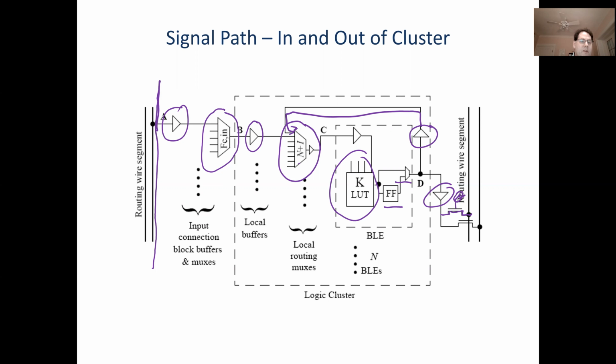The circuit design is pretty reasonable. There's one thing that actually is quite hard to do. This first buffer actually doesn't exist in commercial FPGAs because there'd be too many of them. There are a whole bunch of them and they're really hard to lay out. So generally, you don't wind up with this buffer. You go straight into the multiplexer. That's a small approximation error in the circuit design, but I don't think it affects their conclusions very much.